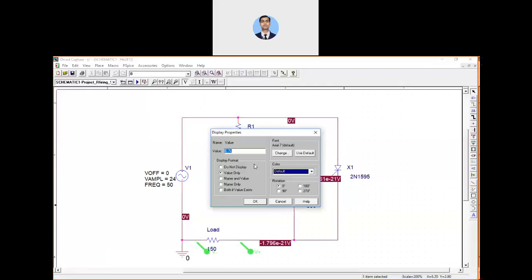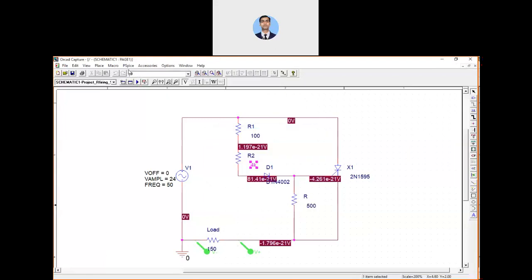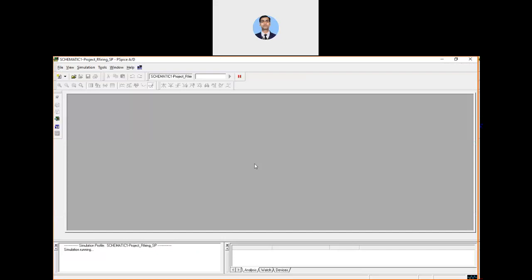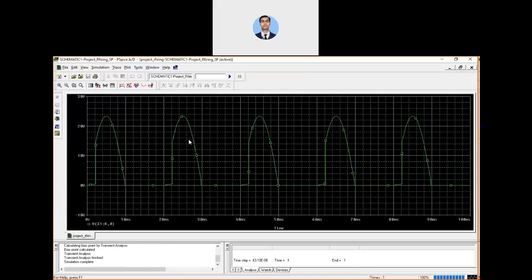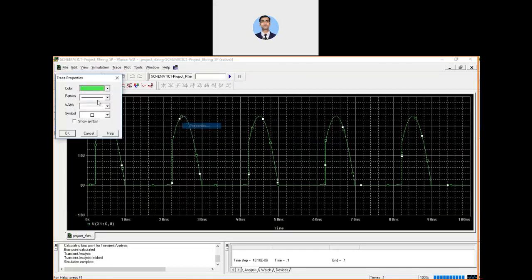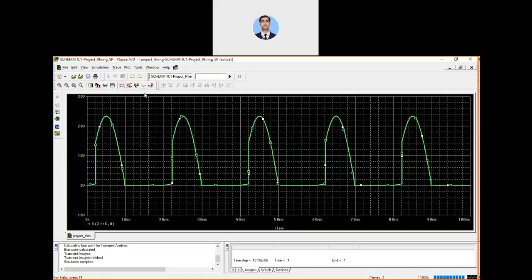Like if I go below this, to 4K, and run this, and get some results with less than 90 degrees, we can easily understand what my firing angle is. Take the toggle cursor and put it at the firing instant, and it is 42.114.